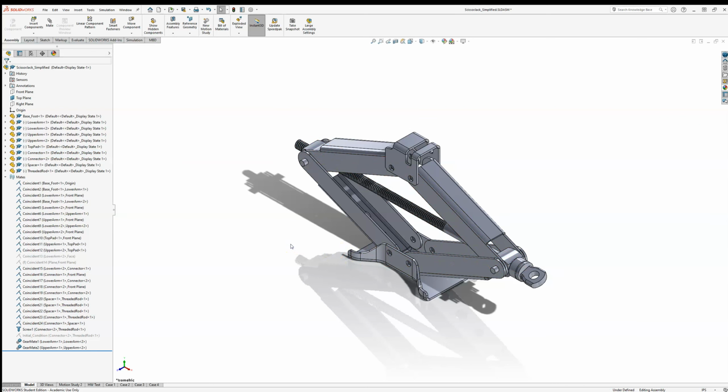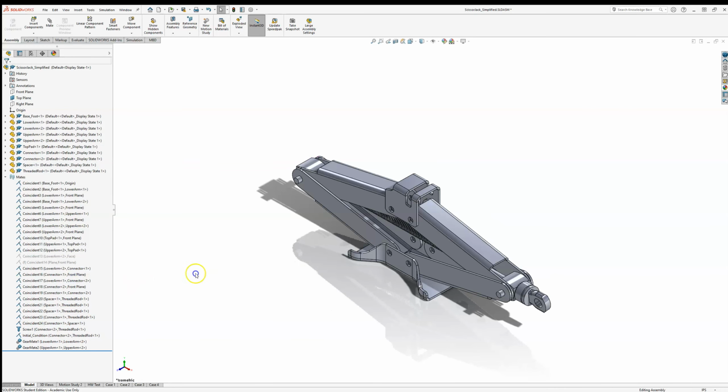And so this is one thing you can do to actually mimic what this thing's going to do in real life. Say you knew the thread properties of the threaded rod, so maybe it's a 1/4-20 type thread nomenclature that you would use there, and then with a little kinematic knowledge you would know that, hey, for every revolution of the rod, the translation of the nut will be a certain value there. And so I can actually bake that into my SolidWorks model itself. And you don't really have to do any math there to figure that part out. That's part of what the software is doing for you. You're just having to describe the properties of that mate to it. And so there's an example of an assembly.